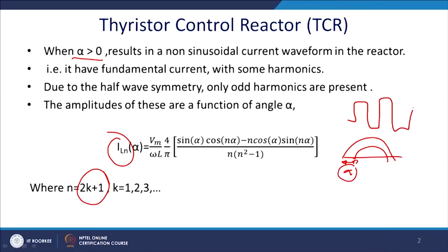something like that. So, we can also eliminate selective harmonics which may pose a threat. We can choose alpha in such a way that a particular harmonic may be removed. Only one harmonic can be removed by it, as we have studied in the case of selective harmonic elimination, when you have only one triggering. Once you have multiple on and off in a half cycle, then we can eliminate multiple harmonics, but we can eliminate only one harmonic here.